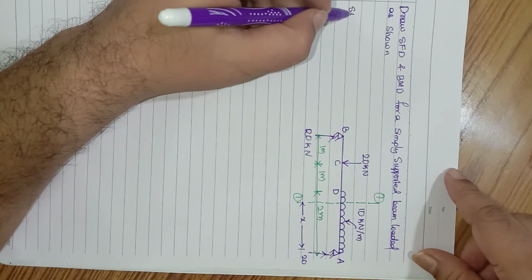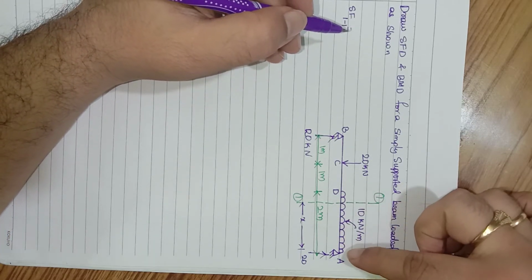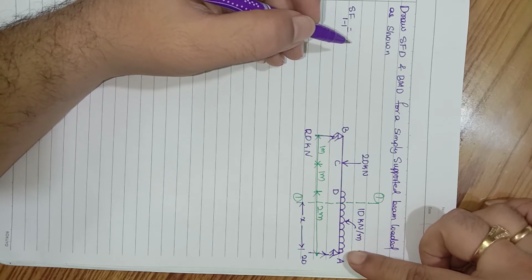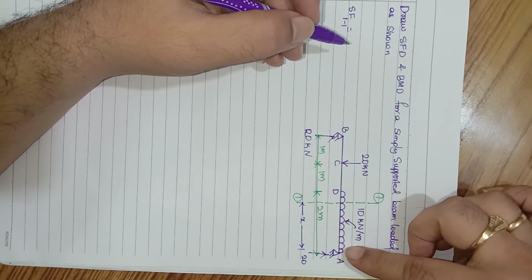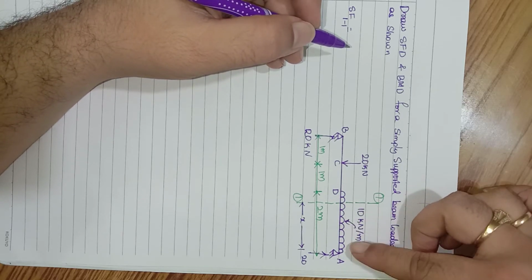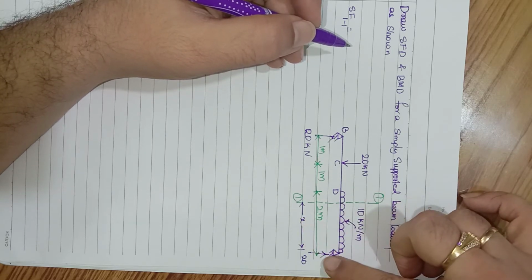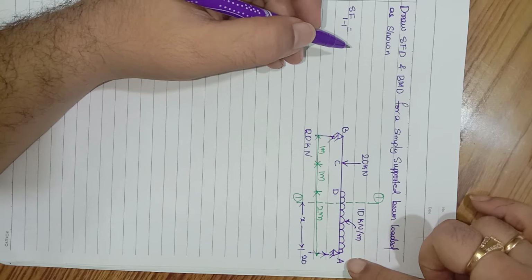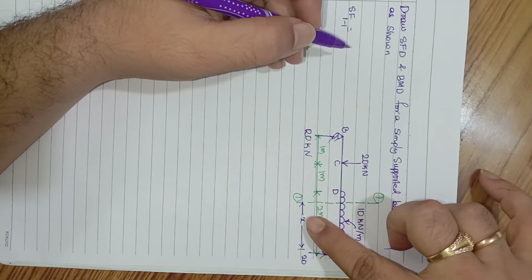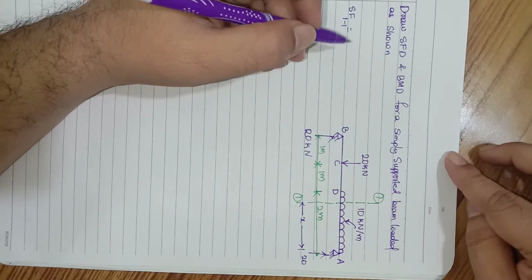Now the shear force at section 1-1 will be found by taking the right side of the section, and I'm going to take the algebraic sum of all the forces. As you know, the shear force is the algebraic sum of all the unbalanced vertical forces acting towards the left or right side of the section. I'm taking the right side of the section. We have 10 kilonewton per meter acting over a span of x, and we have 20 kilonewton. The 20 is acting in the upward direction, so it should be taken as negative. The 10 kilonewton per meter acting over span x should be taken as positive, as it is acting in the downward direction as per the sign convention which I have explained.